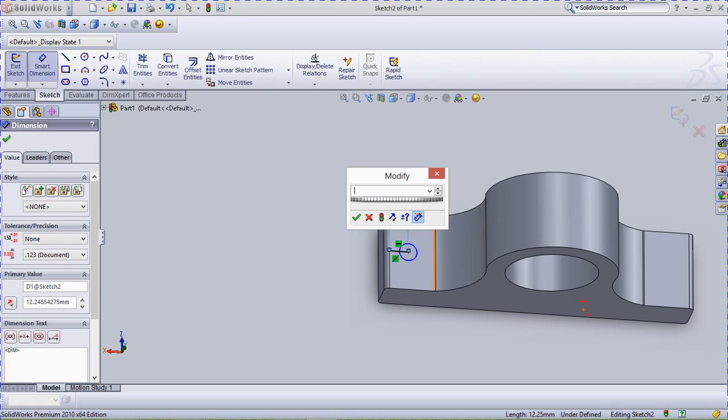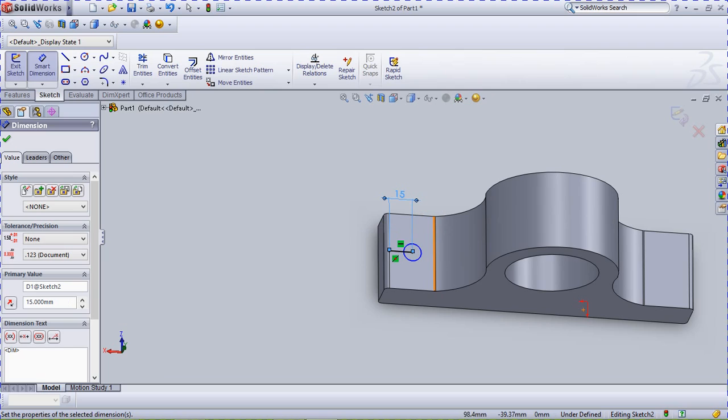So the tear area we have to calculate, which will be 4 to 5 mm for the 10 mm hole. So 18 divided by 2 is 9, plus 4, that should be 13. So plus 2 mm clearance, so 15 should be sufficient.